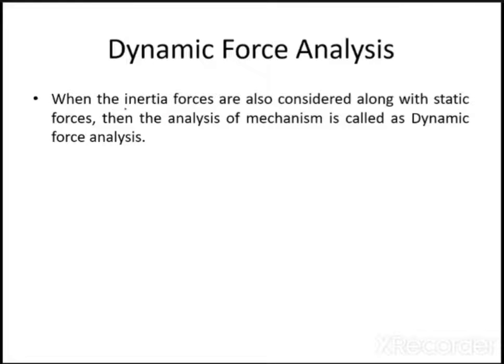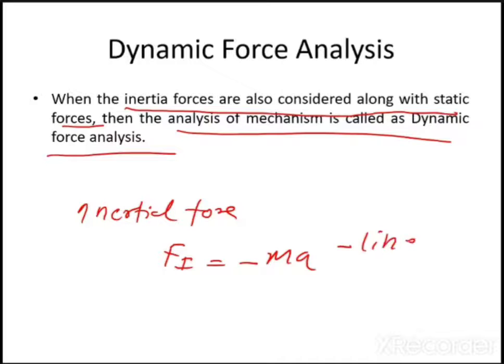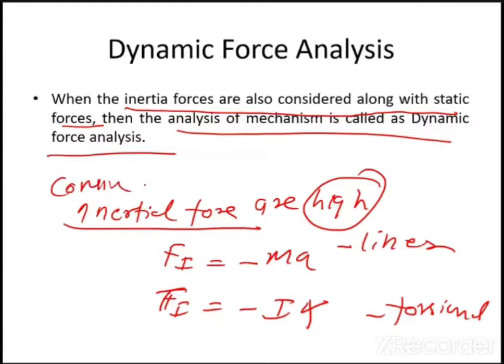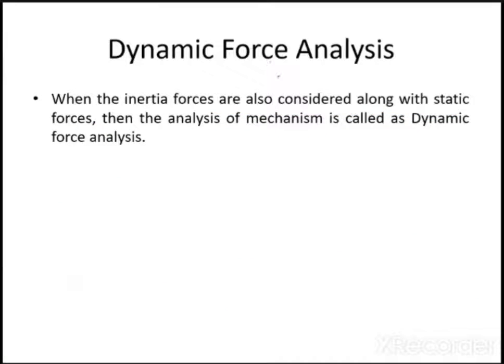When inertia forces are also considered along with the static forces, the analysis of the mechanism is called dynamic force analysis. The inertia force Fi is equal to minus m into a, the exciting force, if the system is linear. If the system is torsional, Ti is equal to minus I into alpha, a torque. If these inertia forces are relatively high and you cannot neglect them, then you have to consider them. Such an analysis is called dynamic force analysis.